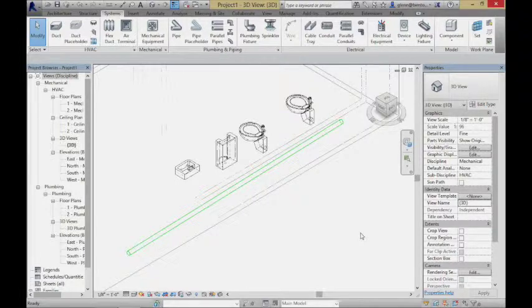I could try to go through and do something called auto routing, where I give Revit a whole bunch of fixtures and say, hey, you figure out the piping. Okay? And you'd be amazed at how either good or frustratingly bad it does with that task. Because taking a whole bunch of outputs and trying to figure out the appropriate piping scheme to make it all work right is actually a pretty sizable task.